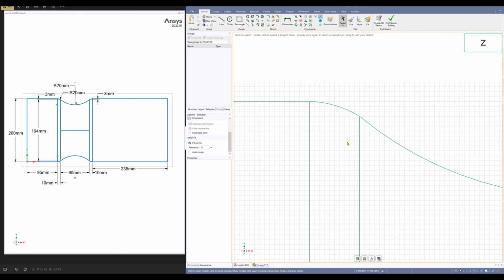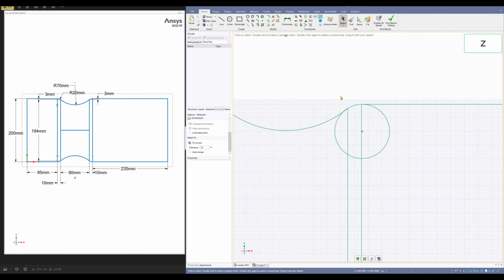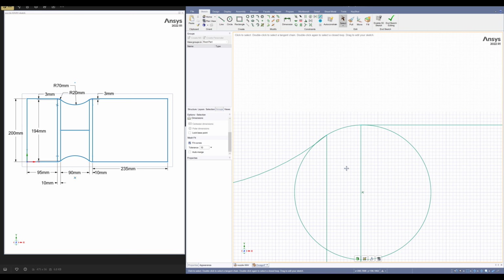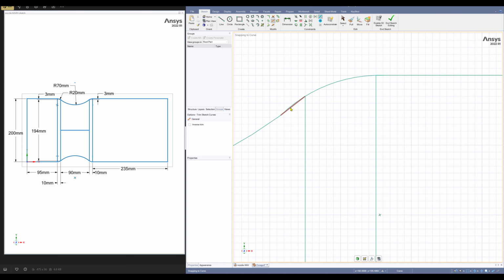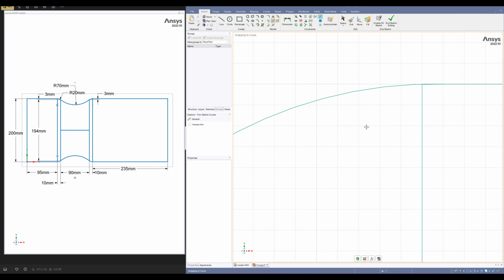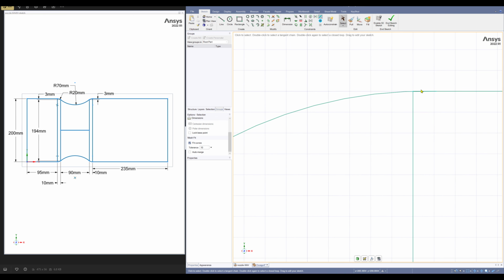Let's click on the screen, and then use the Z key on the keyboard. Now I will do the modification for this circle. Use the trim tool, delete this one and these edges, this extra as well. Then use the escape key to exit from the trim, and then select this arc, or curve actually, and then bring this edge to this point.